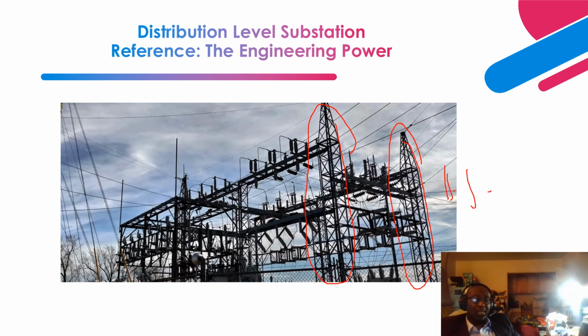On top of this you have a main bus and a transfer bus, a main and transfer auxiliary bus scheme. The main is usually the bus that is energized most of the time. When you have to perform maintenance on the main bus, that is when you incorporate the required switching, and also changes in the protective relay settings, to accommodate transfer to the auxiliary bus scheme.